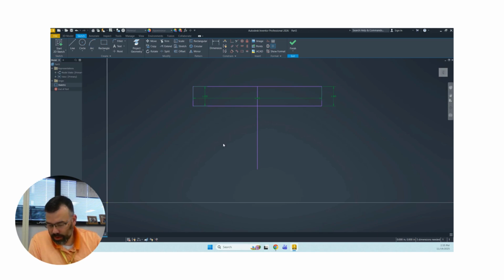how do we want to do this? So I'm going to offset this to the left and to the right 1/2 inch, so then we'll have our 1 inch space in between. So we go to offset, click on our object, and go 0.5, enter. So this is a little different than using AutoCAD offset, 0.5, enter. In AutoCAD, you have to put in the distance first before you select your object. In Inventor, you select your object and then you go direction you want. You can either click to set it down and then modify the dimension, or you can type in the dimension.